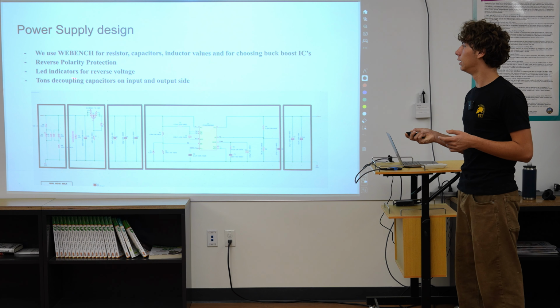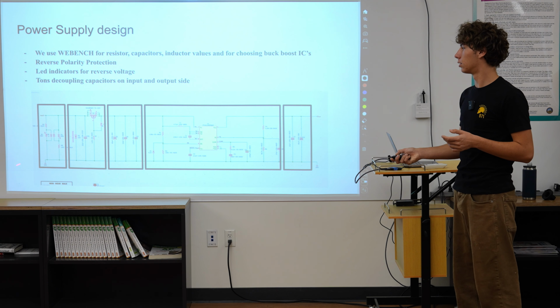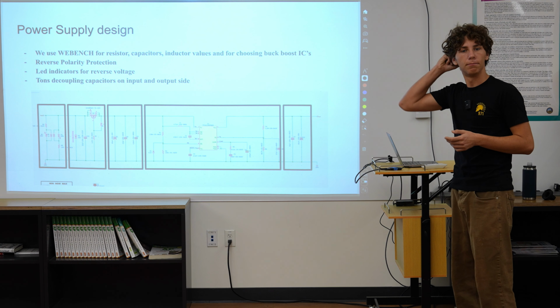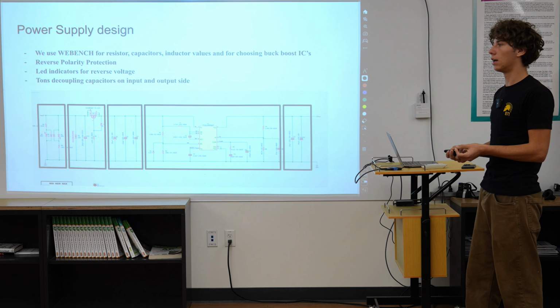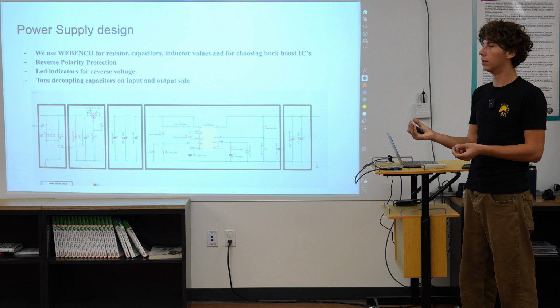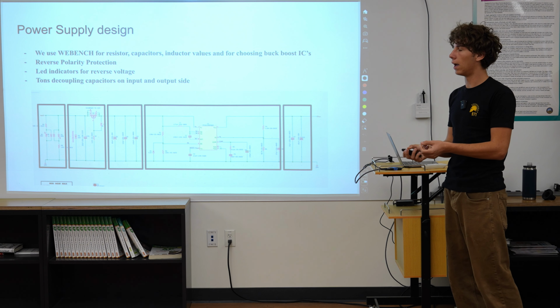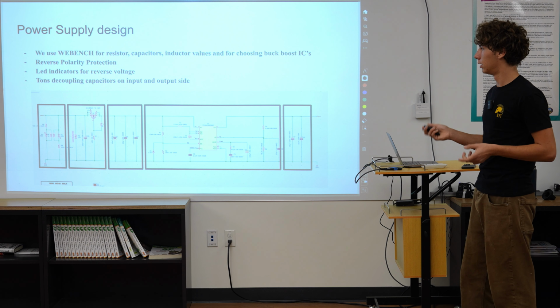We also use LED indicators for reverse voltage. So that's going to be this circuit right here. We usually can't see the silk screen, as I mentioned previously, so having an LED tell us if it's in the right way with green or not with red is really helpful.